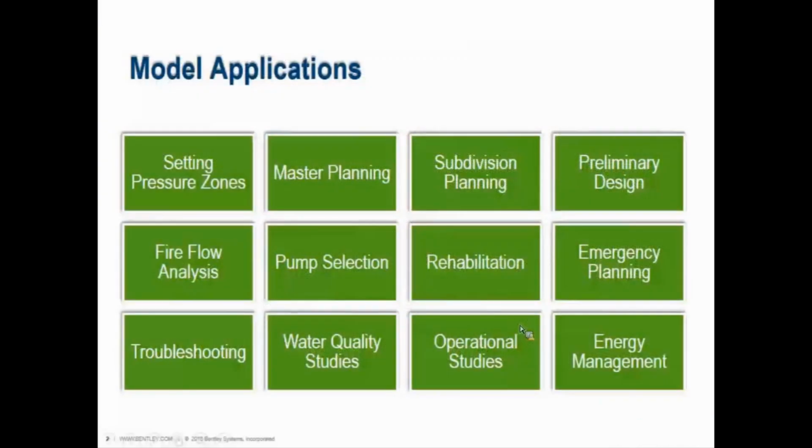So this section, the intent is to cover the many different applications that you can use with your WaterCAD and WaterGEMS model. We're going to talk about system planning, some tips that you can use there, setting pressure zones, using master planning, skeletonizing models, fire flow analyses. We will spend more time on that. Water quality studies and modeling chlorine concentration. That might be something that you might be using your WaterCAD WaterGEMS model for.